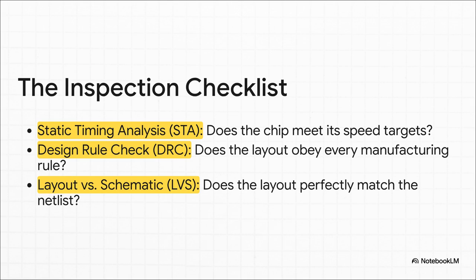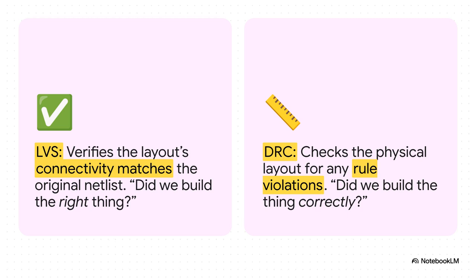Well, there are 3 absolute must-pass tests. First, static timing analysis, or STA, which confirms the chip is actually fast enough. Second, design rule check, or DRC, which meticulously checks the layout against thousands of manufacturing rules. And third, layout versus schematic, or LVS, which makes sure the final drawing is electrically the exact same as our original blueprint.